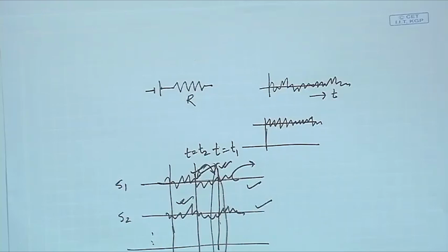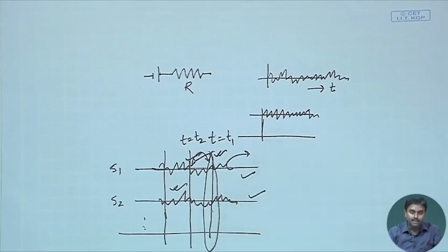So, the associated random process is just that experiment of putting an identical resistor and then measuring the current through it, which is completely generated due to an inside randomness happening, which is called Brownian motion. Okay. Due to that, whatever current is happening for the entire time duration, if I record the overall sample function, those sample functions are now random, because as you have seen, one particular sample function is quite different from the other sample function.